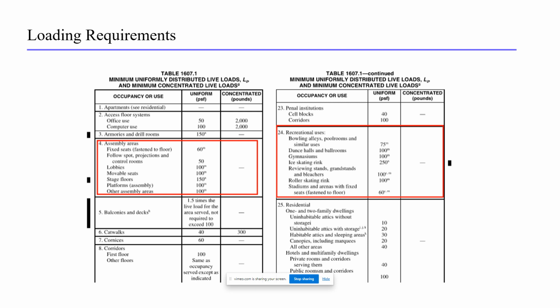Note also that concentrated loads should not be converted to uniform loads. For example, as we were talking about for stages, this often becomes the case where we have a lift, a 2,000-pound man lift, for example, which should not be divided by the surface area that it occupies and compared to the uniform load rating. Why? Because the concentrated loads on the wheels can cause much more acute local stresses in different failure modes. So you need to evaluate that separately based on the equipment.